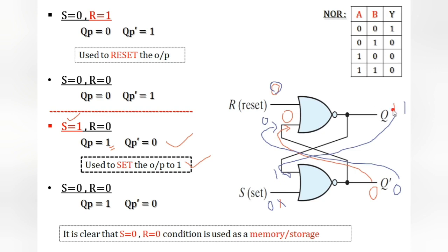So listen. In the first condition my outputs are 1 0. In my second condition my outputs are again 1 0. So here I have given input 1 0. Again I am erasing my inputs. So after erasing inputs, outputs are the same. That is nothing but this circuit again acts as a memory element. So it stored the previous data. Here the previous condition is S1 R0. In this case the previous inputs are S0 R1 condition.